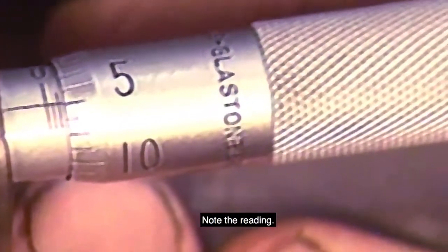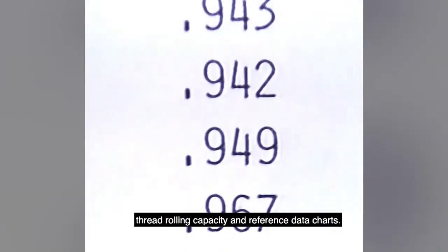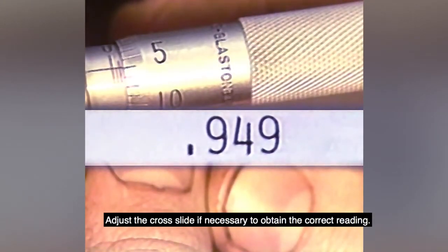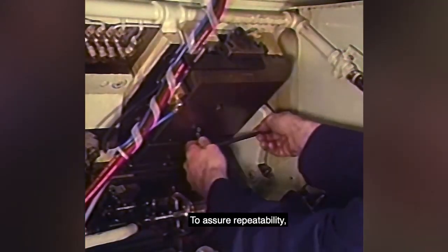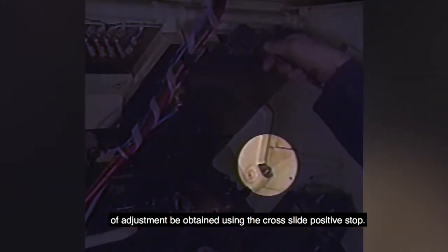Note the reading. Obtain the correct gauge setting from the thread rolling capacity and reference data charts. Compare the reading that you've taken with the correct gauge setting dimension. Adjust the cross-slide if necessary to obtain the correct reading. To assure repeatability, it is recommended that the last 3/1000ths to 5/1000ths of adjustment be obtained using the cross-slide positive stop.